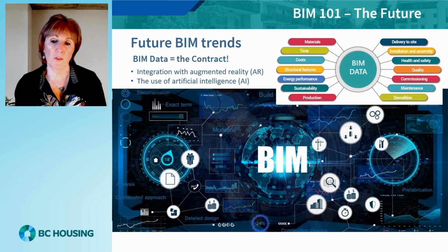As we move into the future and BIM becomes the norm, it is predicted that the data fields will have as much value as the geometry, with contract documents adjusting to include the model dataset as part, if not all, of the submission. This shift will require the normalization of the data so that all parties can access and use it in any software solution. This will require all model datasets to be in compliance with the industry global standard, which is currently IFC 4.3.